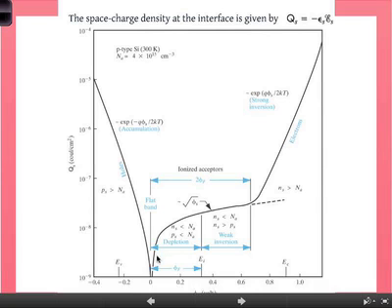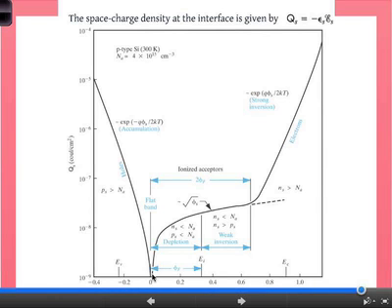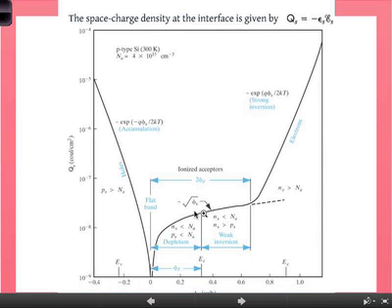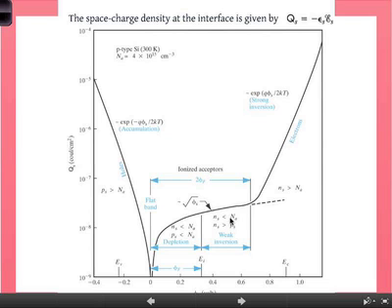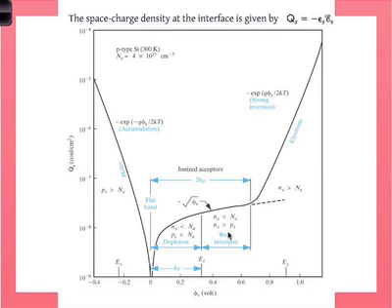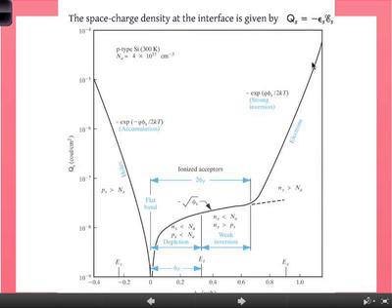Okay. Now, on the other side, as you make the gate voltage more negative, you're depleting it. So you're pushing the holes away, you're exposing the ions. This is the so-called depletion region where you have a slow increase, something like a square root in this case. And at some point, you start inverting it, which means you start creating more electrons, a weak inversion. Make it a little bit n-type. And at some point, it becomes strong inversion. You attracted so many electrons that it becomes very strongly n-type. And that can increase exponentially. Okay? This part is the so-called triode or linear region that we saw in our water analogy, and that's the saturation region, when you actually have a channel.